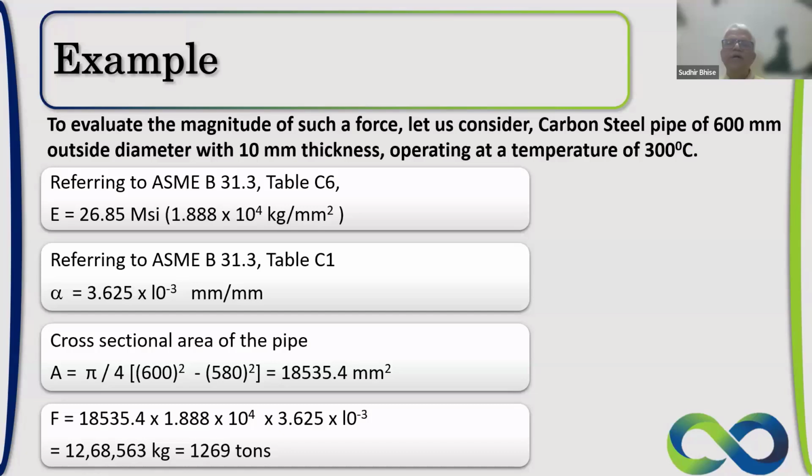And if we do not allow for that displacement, then we are going to get a tremendous amount of forces on the connected equipment or support, or even in some cases the delicate equipment, which may not accept this heavy amount of loading on the system. Now, when we saw these tables, we know the criticality of the system.